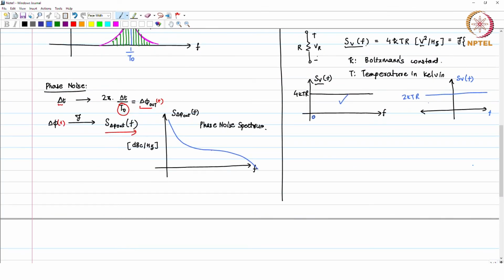I can at any given time mimic a noisy resistor R between two potentials A and B. This noisy resistor is equivalent to a noiseless resistor with a voltage source V_NR in series with it, between A and B. There is no polarity to this voltage source because it is a random signal, whose power spectral density is 4kTR.